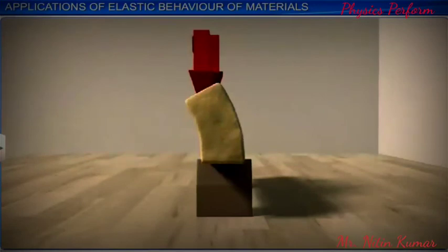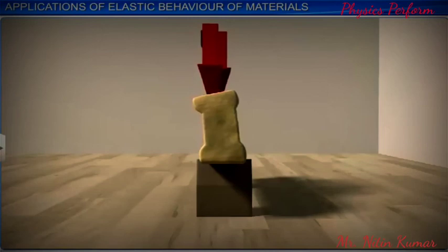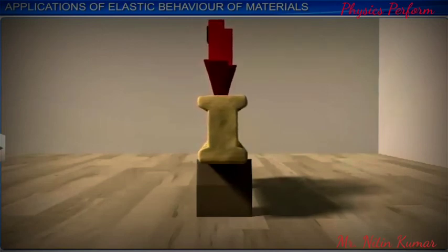This shape provides a large load-bearing surface and enough depth to prevent bending. It also reduces the weight of the beam without compromising on its strength to bear loads. The pillars used in buildings and bridges are also modified to be able to support greater loads by making the ends distributed.